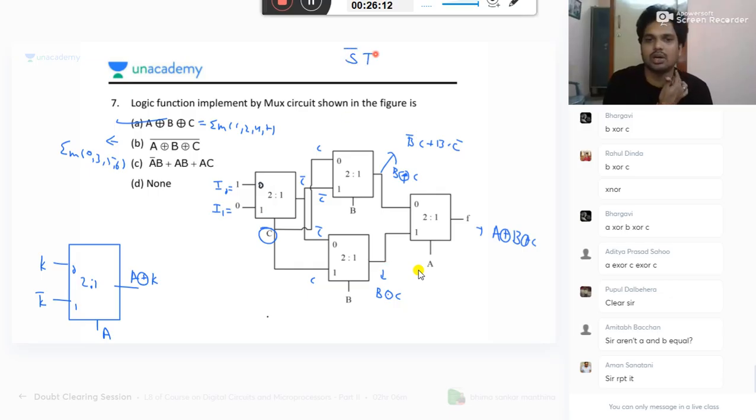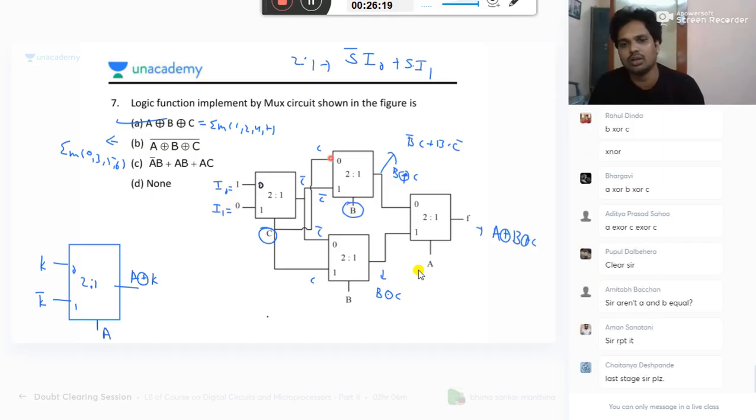What is the D option? Someone having doubt. Vi equal to 0. Is 0 greater than 2? No. So R is equal to 0. What about S? 0 is greater than minus 1, so this is also 0. Here it can be either 0 or 1. Actually, no change. It is a no change condition. D is also correct, but out of the options you want to select the best, which is B. P can be either 0 or 1, definitely correct technically, but if we say no change, it is better. Go for B, which is more perfect.